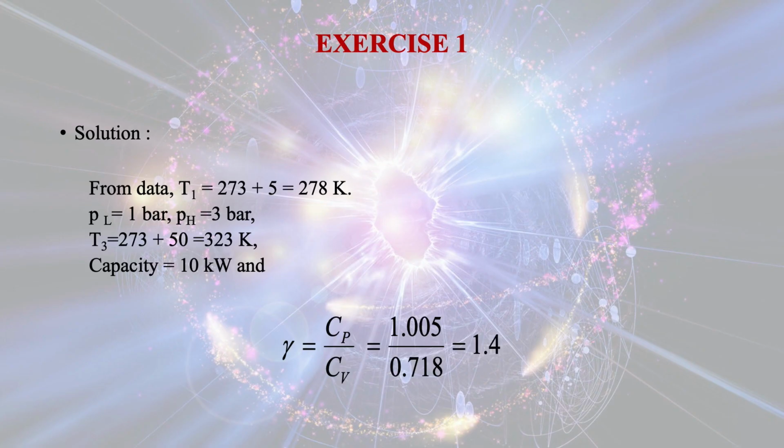So in this case, there is compression work, that is equal to H2 minus H1. There is turbine work, that is equal to H3 minus H4. There is net refrigerating effect, that is H1 minus H4. Now, dear learners, let us see how we can proceed further for solving this very interesting numerical.